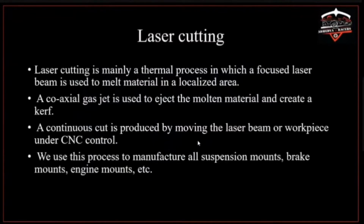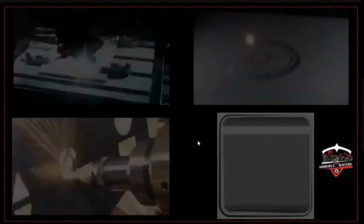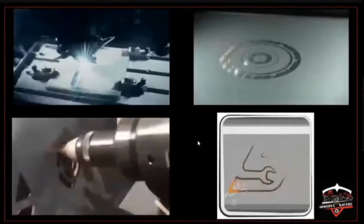Laser cutting. Laser cutting is mainly a thermal process in which a focused laser beam is used to melt material in a localized area. A coaxial gas jet is used to eject the molten material and create a curve. A continuous cut is produced by moving the laser beam or workpiece under CNC control. We use this process to manufacture all suspension mounts, brake mounts, engine mounts, etc. These clips show us the laser cutting process.